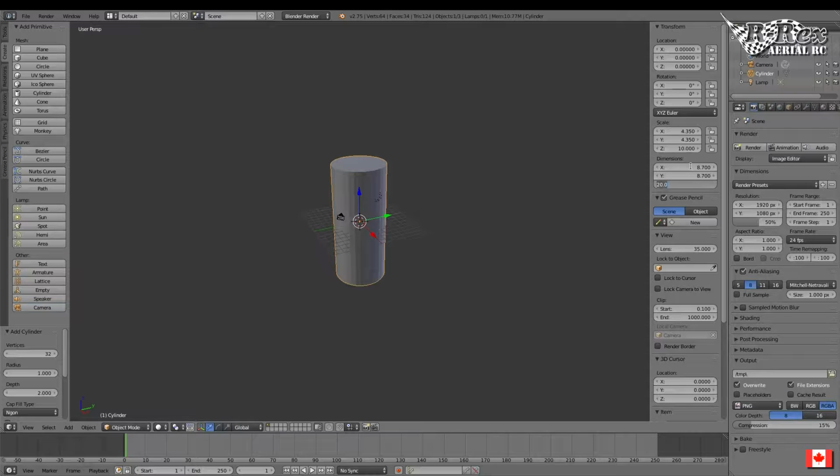I'm going to leave the height pretty close. Now, actually, I am going to modify the height just a little bit. I'm going to drop it down, let's say 1 millimeter, so I'm going to go to 19. The reason for this is the motors are actually tapered on the top. I want this motor to sit inside of its connector. So I've taken 1 millimeter off, but I'm going to add that millimeter back to it.